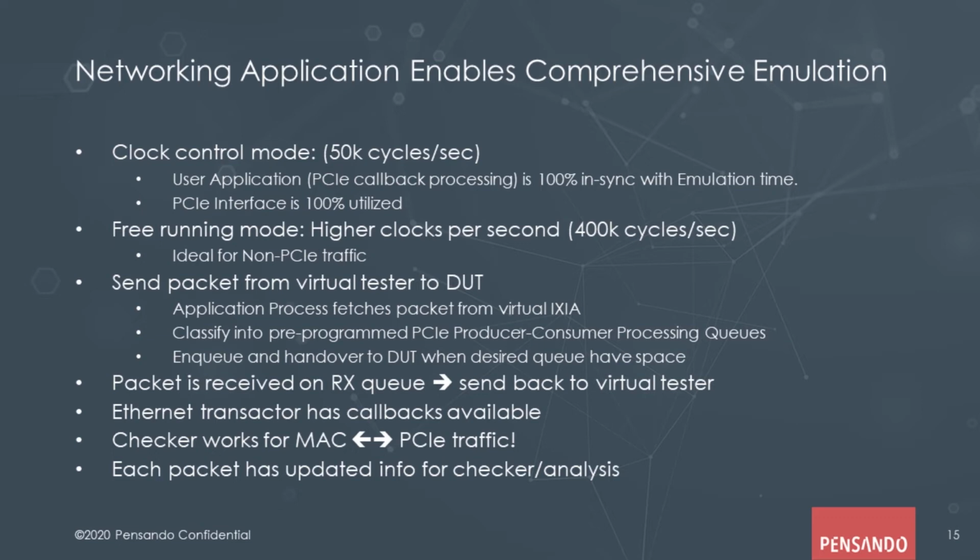You first check which producer-consumer queue it came up on, and whether it came up correctly on that or not. So you apply a checker there. Once the checker passes, you do some measurements like latency, bandwidth, etc., and then you hand it over to IxVerify. Now IxVerify does report latency, in-order check, and other Ethernet packet-level checks, so that is already taken care of by IxVerify.